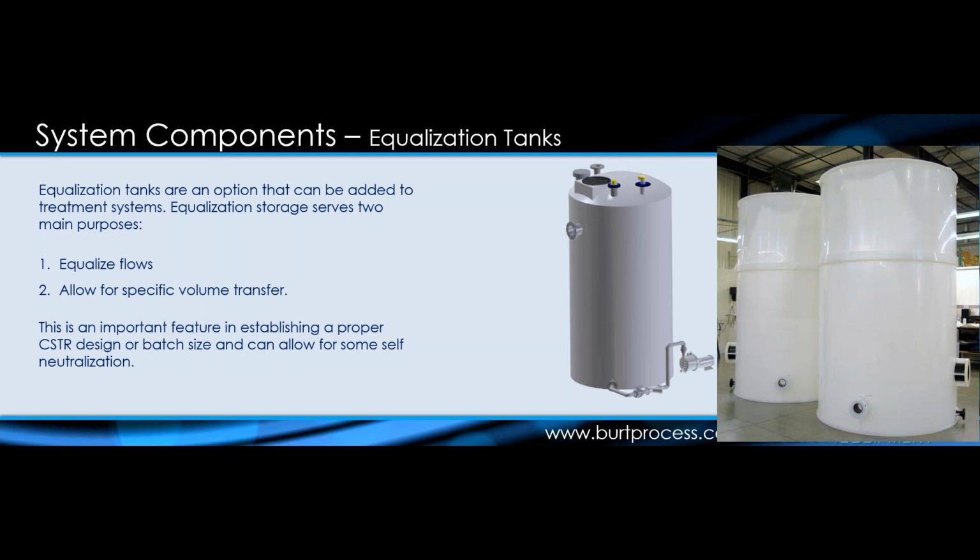One system which really ties into pH systems, although it's not directly a part of it, is equalization tanks. For the most part, we've been talking about the pH system, the tanks, mixers, the pH instrumentation. Equalization tanks are generally used to help size and/or control the pH adjustment going on within your actual system. Equalization tanks are storage vessels that go upstream of your system.